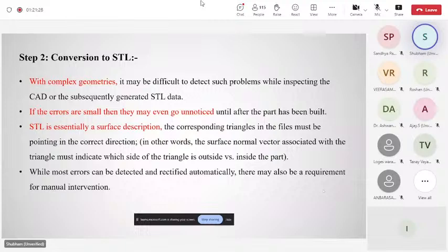Many CAD software packages have repair tools which include automatic error detection, and which rectify the errors and try to improve the model. These tools can identify common errors such as non-manifold edges. If there is an intersection between two triangles, many software packages will detect it, and if it can be changed, it will be improved automatically.